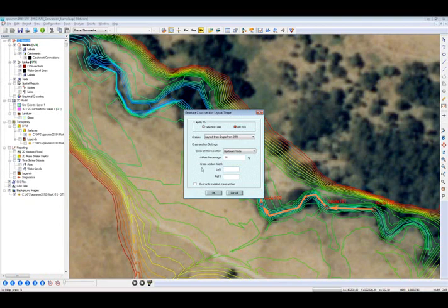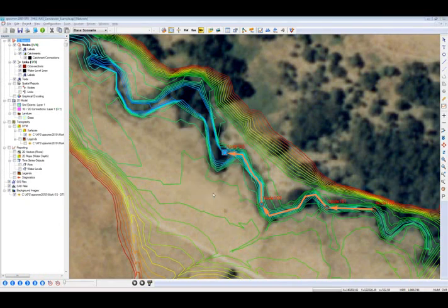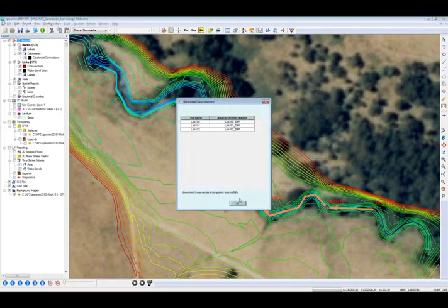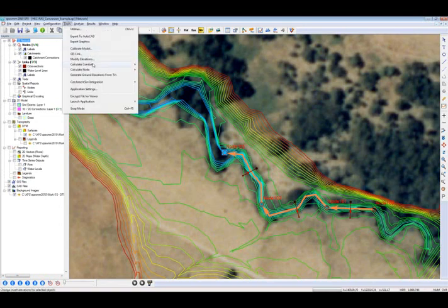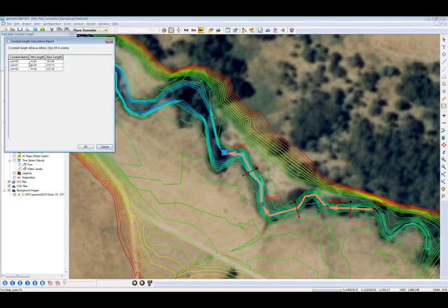And I believe the river is about 50 feet wide, and so we're going to have the left bank be roughly 30 feet, right bank be 20 feet. So you can see here it automatically allocates those shapes, and these shape markers show where that was draped, and these red and black nodes indicate the right and left bank used. From here, again, the calculate conduit option, calculate lengths,